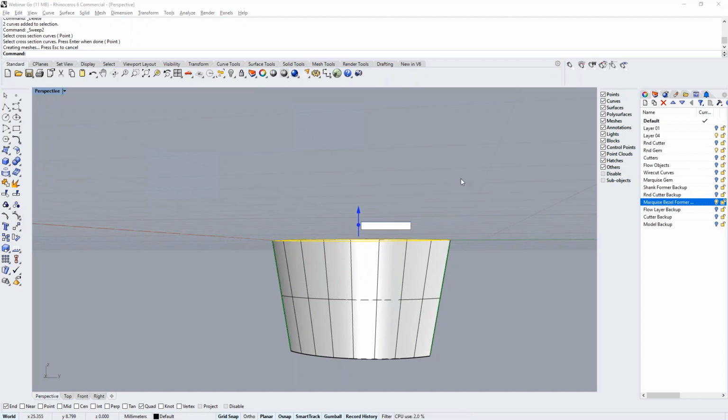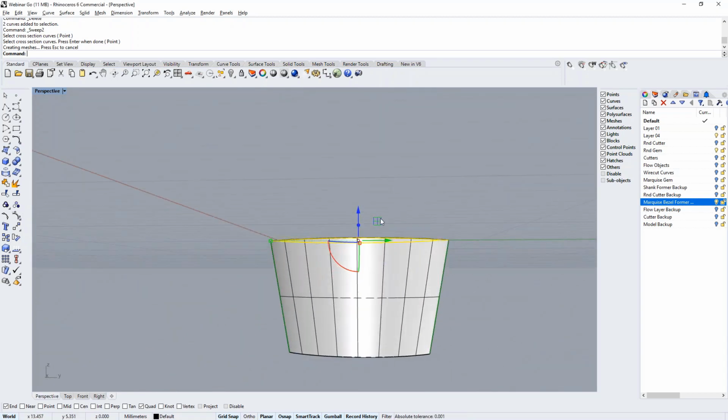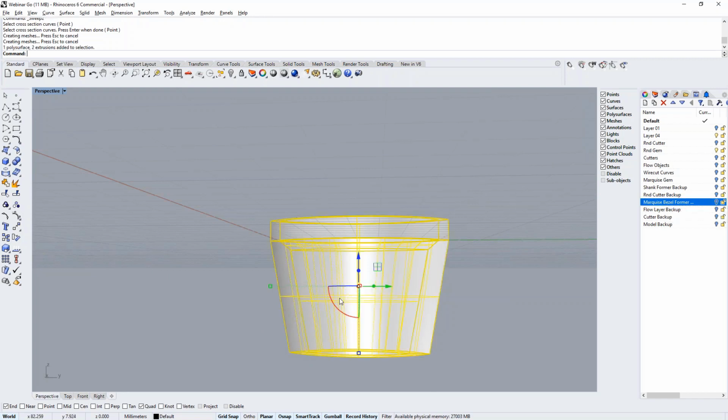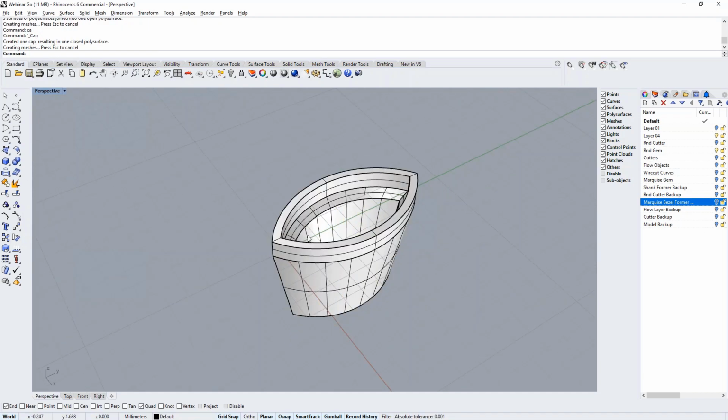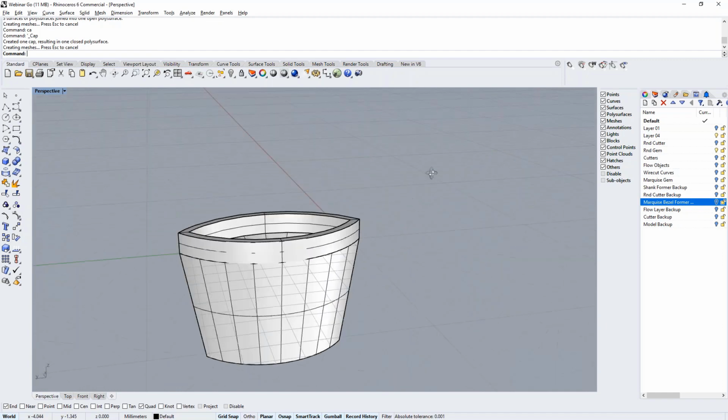Those two curves, you can see that I have selected here. We'll extrude them up using this 1 millimeter, right? And now we can take these curves away because we don't need them anymore. We'll select all those, join those surfaces, and cap planar holes. Boom. And there's our bezel, just that fast, just like that.